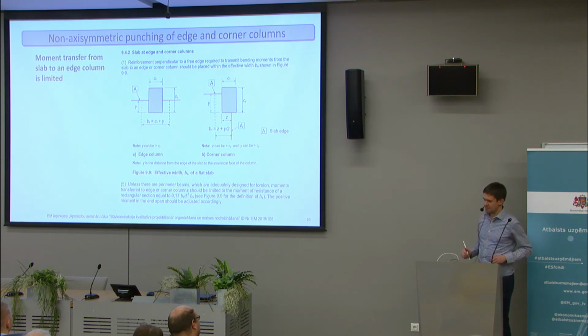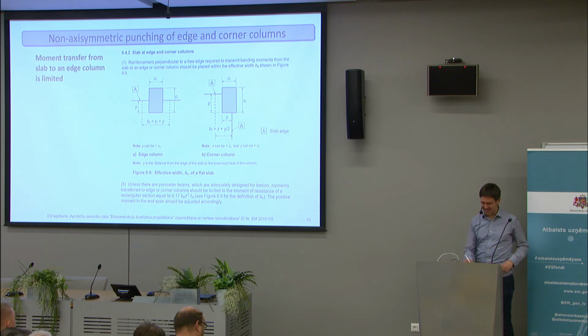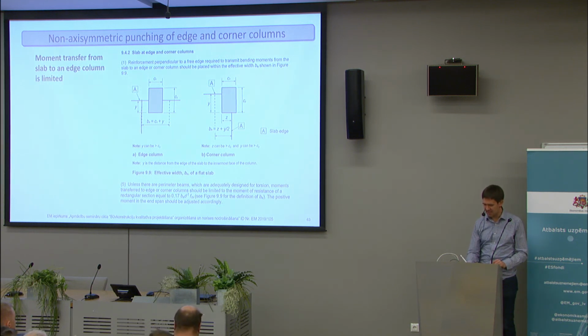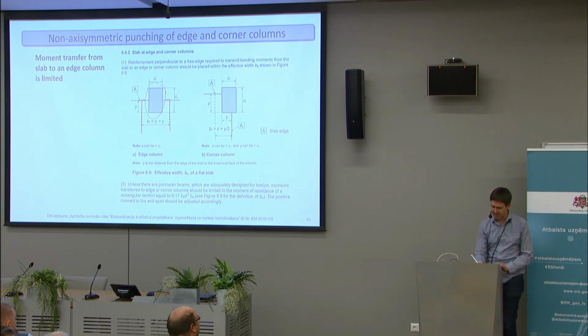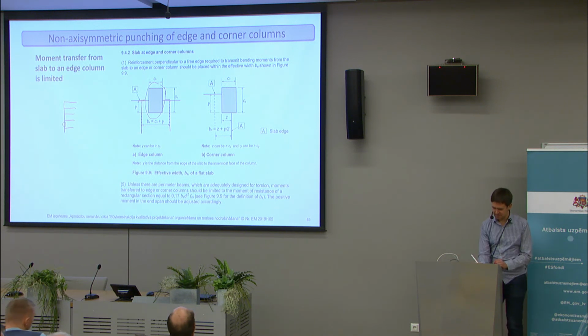Now, in the Eurocode, if you read it until the end, also the appendixes, it gives a limit of how much moment can be transferred from the slab to the column at all. So it gives some indication of how you should calculate these columns, because sometimes, like in one project that we have, on top floors, if you look at the amount of reinforcement in the edge columns, in lower floors you have large normal forces and quite large moments.